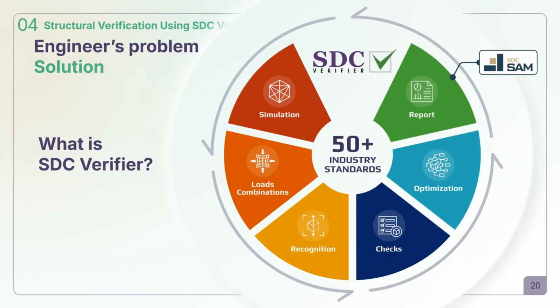cycle or workflow, where engineers start with simulation. So the model has to be prepared with all the boundary conditions and loads, as we discussed. Later on, SDC will help you significantly decrease the load combination time, which will also allow you to do linear combinations, excluding your solver, whether it's ANSYS or Nastran. All these linear combinations can be done directly in SDC, which decreases the calculation time significantly. Of course, if we speak about linear outputs, but non-linear output sets can also be combined, but not with the use of factors,